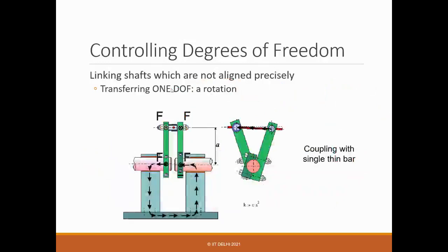So in principle, how can you do it? You are talking about the rotation, but if you move away from the axis of rotation, it's equivalent to a translation constraint. And if it's a translation constraint, it means that it's possible to constrain it just by a pin or a bar, or even a wire, right? And that's the beauty. So try to visualize that.